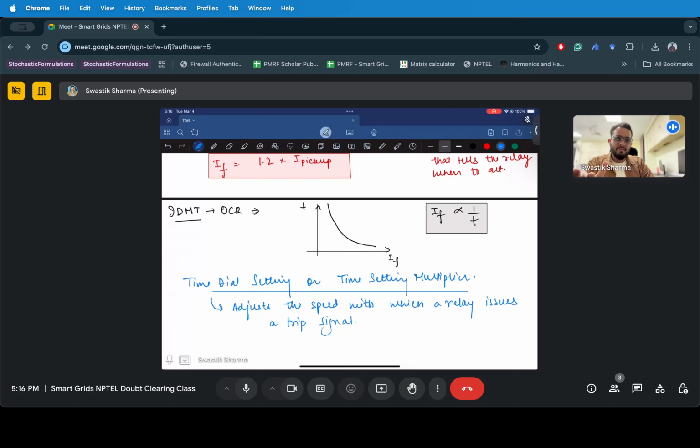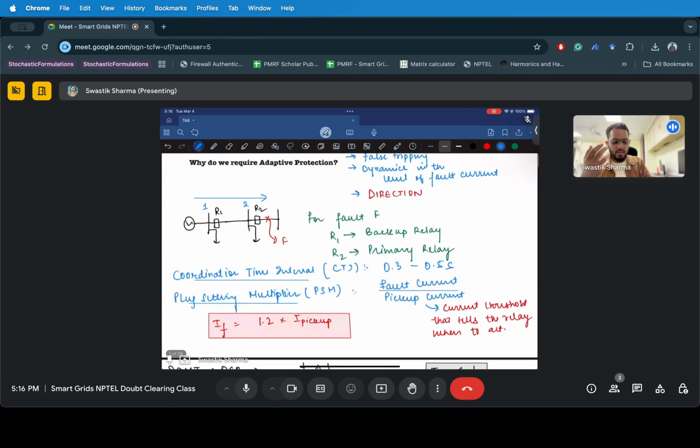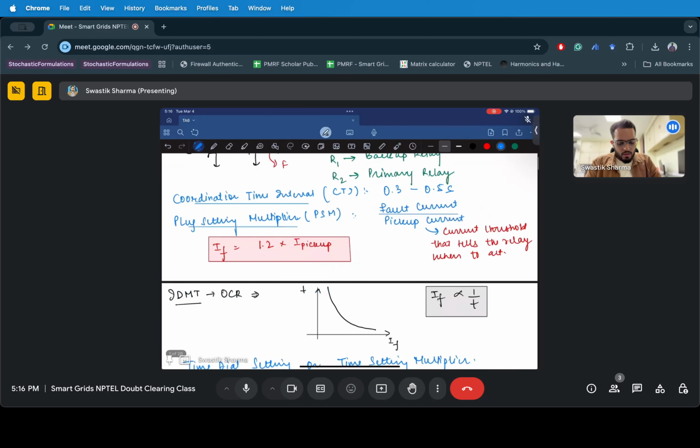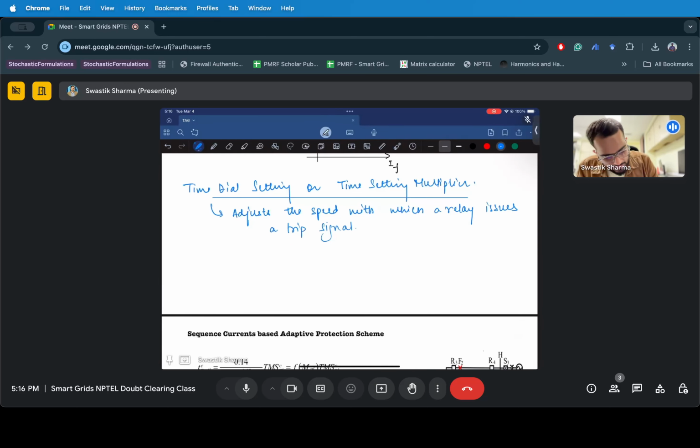And you have to have this adaptive protection because of the dynamics that are now coming into play due to the proliferation, or increasing usage, of DRs at the distribution side, right? So for smart grids, at least, researchers have proposed a new relay, which is called a directional overcurrent relay, also called DOCRs.